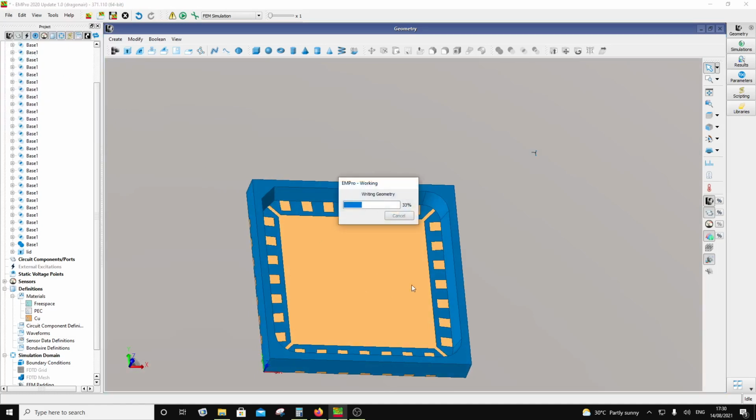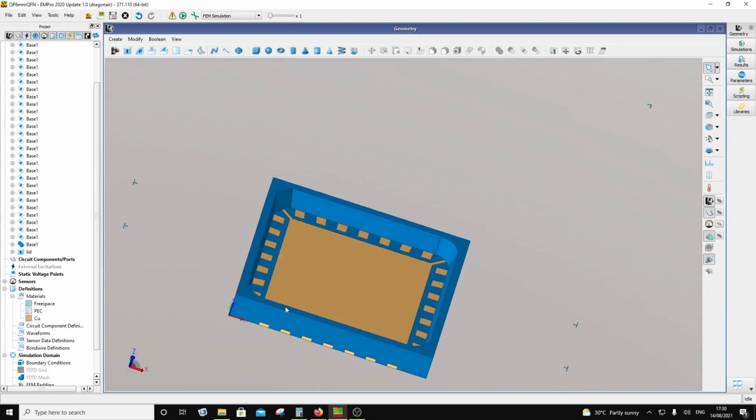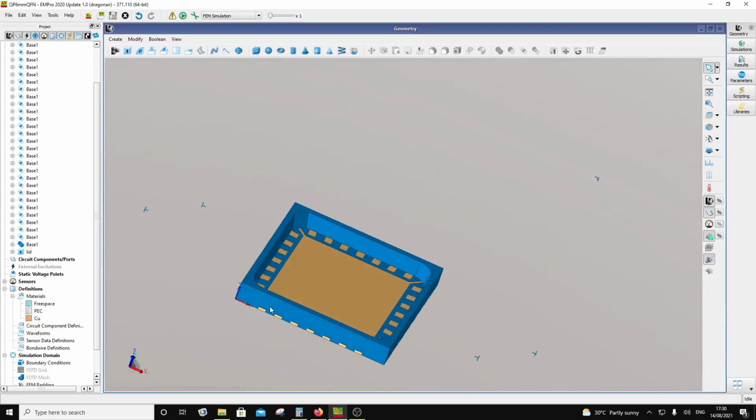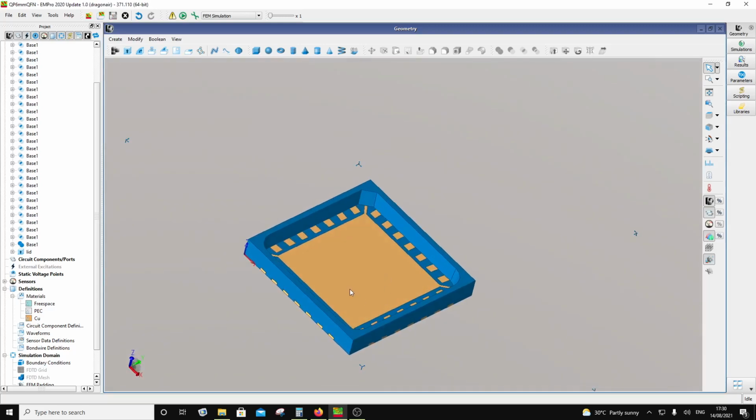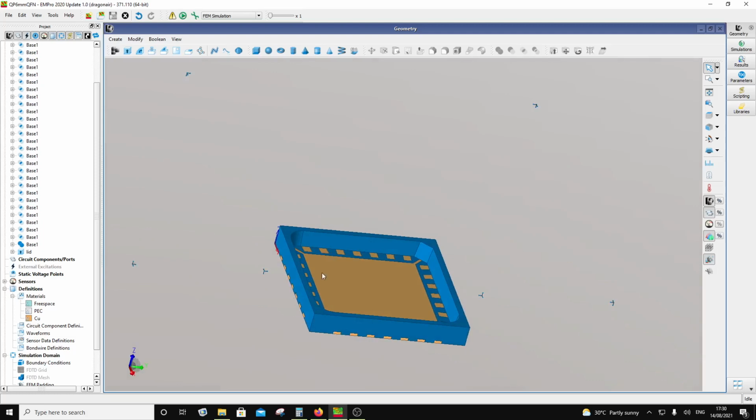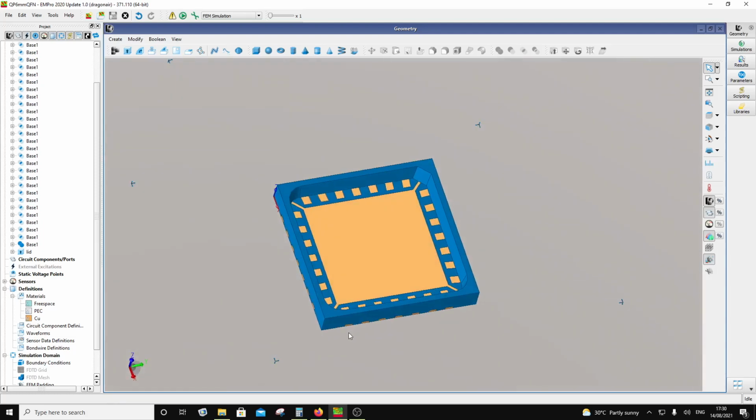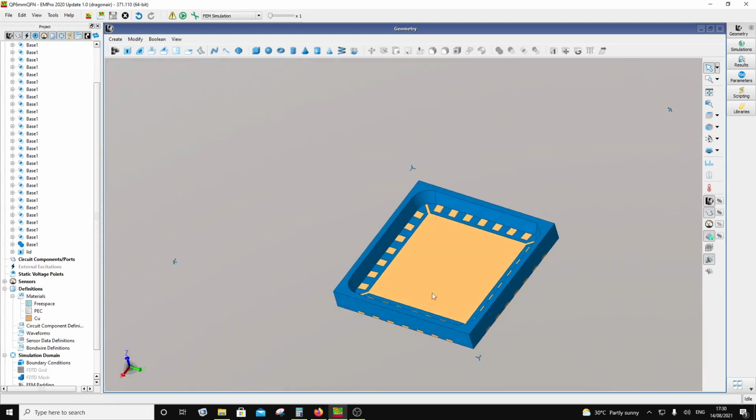Okay, and then you can also change the material which you assign. You can assign this to be a ceramic. This can be a borosilicate, which is your LTCC process. Usually they are done by HTCC. Then they can also be done by LTCC if this is ceramic. So a ceramic package, for example, will go up to almost 100 gigahertz. The packages can go up to 100 gigahertz.